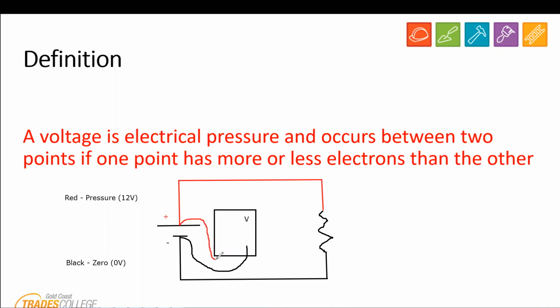When we talked about current last time, we make sure the current flows through the tester. So the ammeter would go in this area here. It would go on there. Okay, so the current's got to go through it. So if you notice, your red cable would go to the red, and your black cable would also go to the red. So this is connected in series.